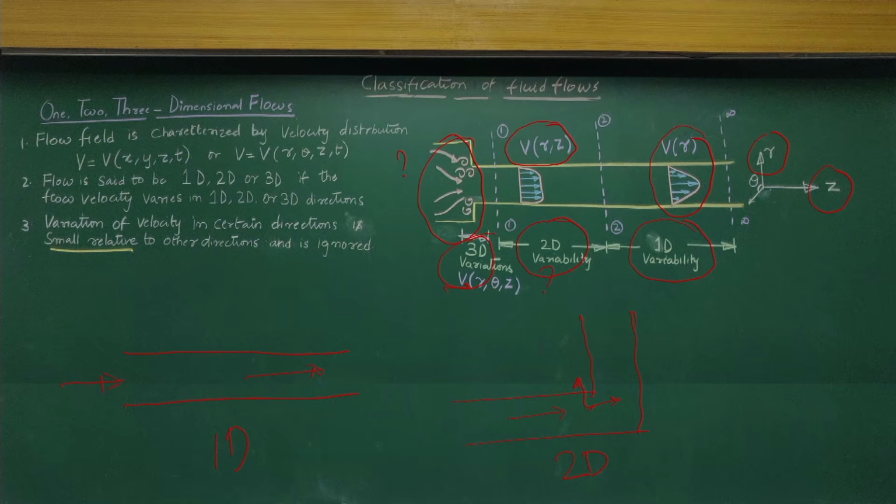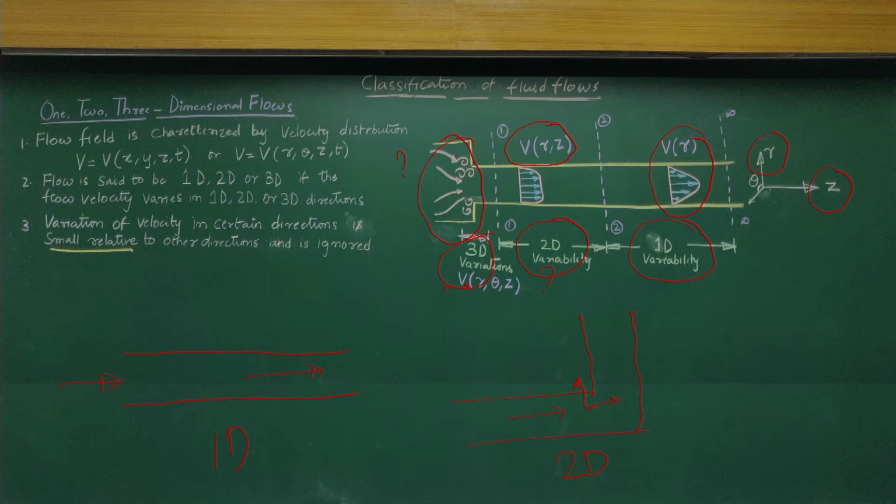Here, the idea is to understand, whether it is one-dimensional, two-dimensional, or three-dimensional, the flow field from the experimental data or the flow field given by any computational technique like computational fluid dynamics. We can understand what type of flow is happening, what type of velocity components are happening, and then we can simplify it. Is this a one-dimensional, two-dimensional or three-dimensional flow? As we simplify, we go from complex to simpler, and we can solve the problems in a simpler way as compared to going for a three-dimensional way.